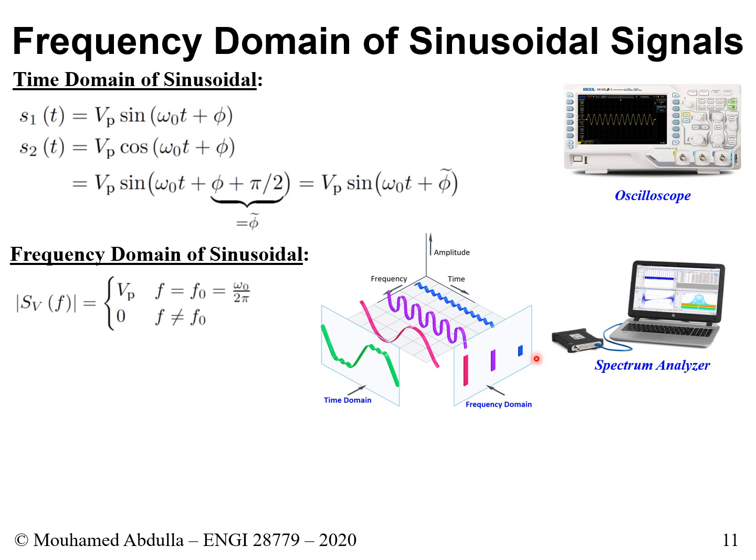It's not in power. And then this one here, the x-axis in the frequency domain, this is in frequency. But if you look at a spectrum analyzer, the spectrum analyzer does not give you the value in voltage. The y-axis with the spectrum analyzer is not in voltage. The actual value with this one or any other spectrum analyzer is always in dBm.